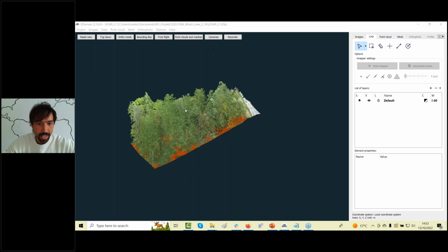Daniel Delsa asks, is it possible to use different cameras in the same project? Yes, of course it's possible. 3Dsurvey covers any camera, any device. Just import all the images into the same project and do the processing. For example, you can use a drone to do drone imagery, and you can create a video and extract some frames from the same area, then run the frame extractor in 3Dsurvey, copy those frames into the same project where you have drone data, and import all of them in the same project, and that's it. Not a problem. You can combine more cameras, it works super nice.